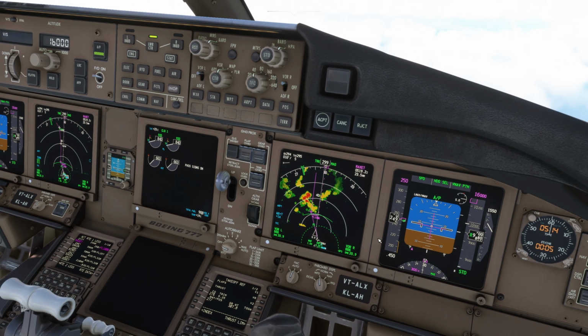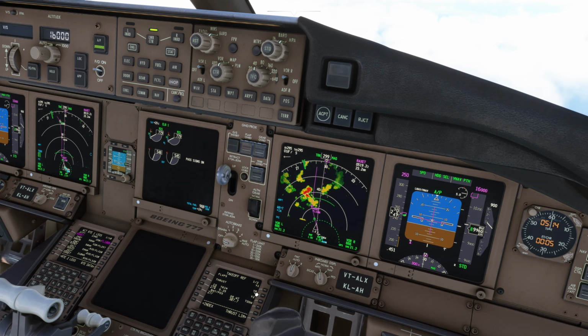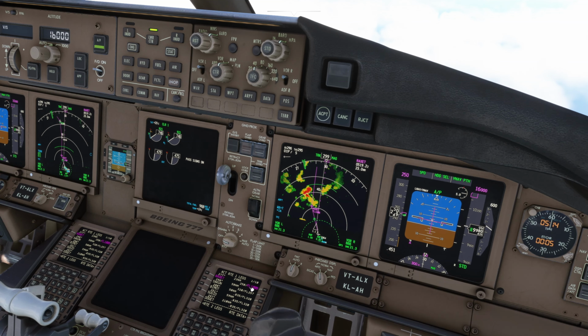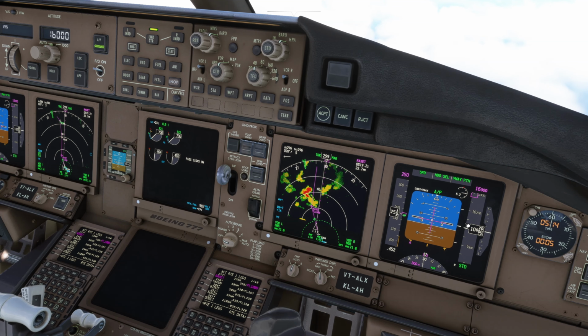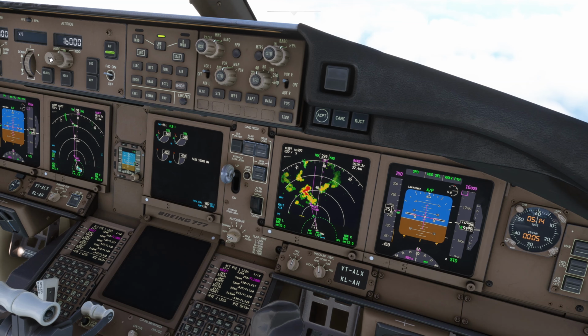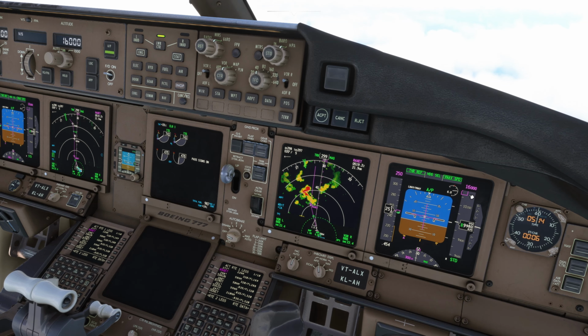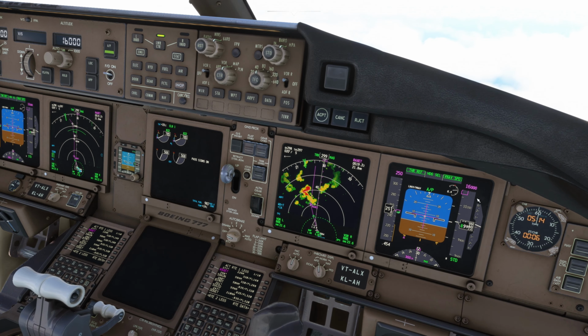do this. So now the airplane will try to level off at 100 because there's a restriction over Rexet at flight level 100 and below. So that's why it has stopped the climb. So what I'll do is I'll just press this, altitude selected. So now you can see thrust, VNAV speed. Now the airplane will climb to flight level 160.